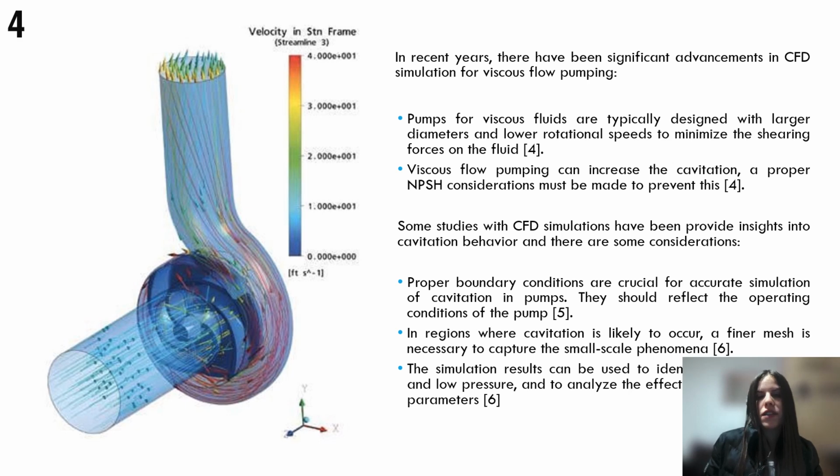There have been significant advances in CFD simulation for viscous flow pumping. Pumps for viscous flow are typically designed with larger diameters and lower rotational speeds. Viscous flow pumping can increase the cavitation. A proper NPSH consideration must be made to prevent this.